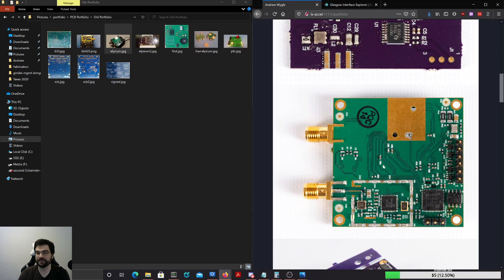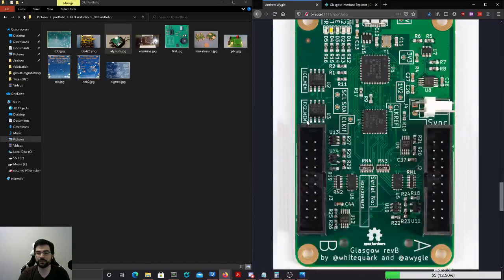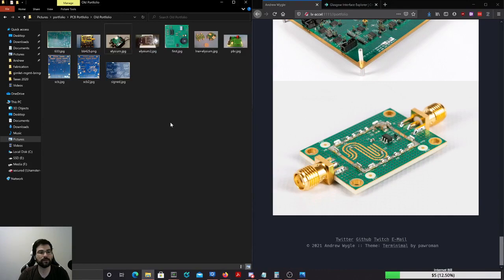So it turns out that this board didn't need any heat sinking at all. It would just happily dump all 5 watts into the board, and eventually the board would come up to temperature, but that would take hours. Normally you would have to pay so much extra for that it's not even funny. I think they honestly just screwed up. But if you took a bandsaw and cut through this thing right here, you would find these just solid cylinders of copper, which I find hilarious, but probably no one but me does.